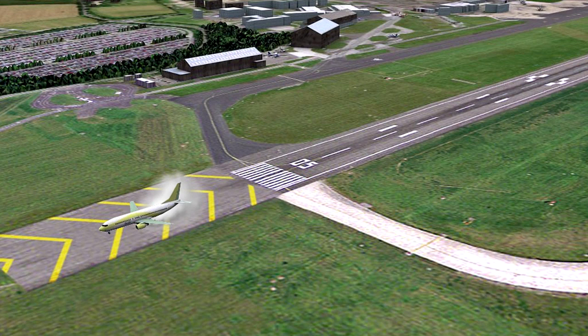A stopway is regarded as being provided for infrequent use, and it consequently need not have the same load-bearing or wear-resistant qualities as the runway with which it is associated. In some cases, the natural surfaces will be adequate, while in others some land drainage, perhaps ground grading, or even light paving may be required. At some aerodromes, a stopway comprising of natural surfaces may be usable only on a seasonal basis. It is essential that you check the aerodrome information for such details.